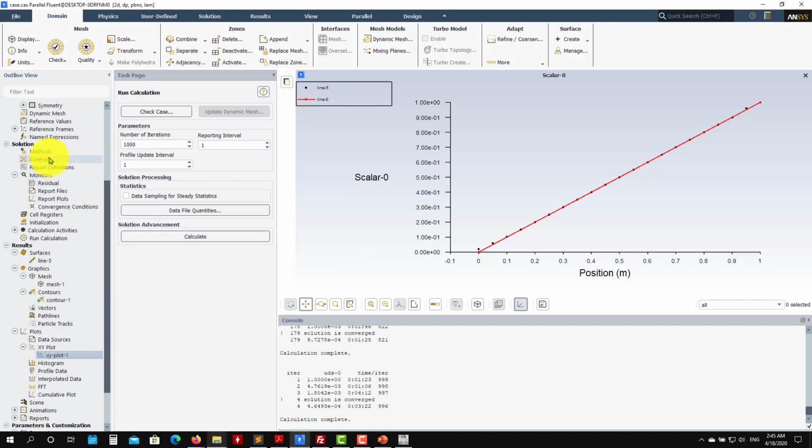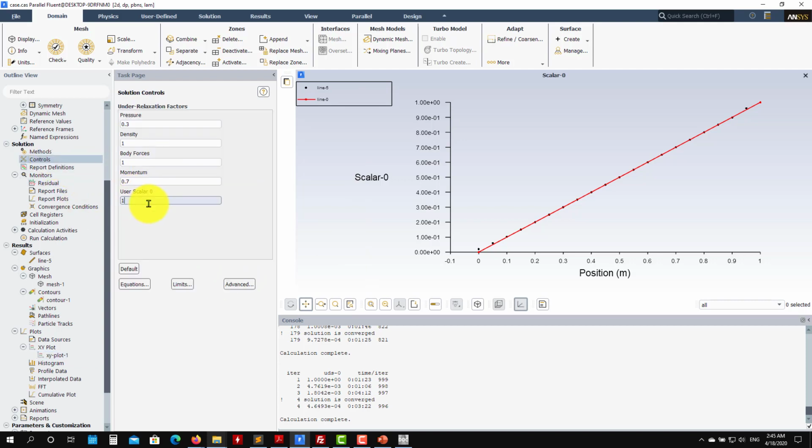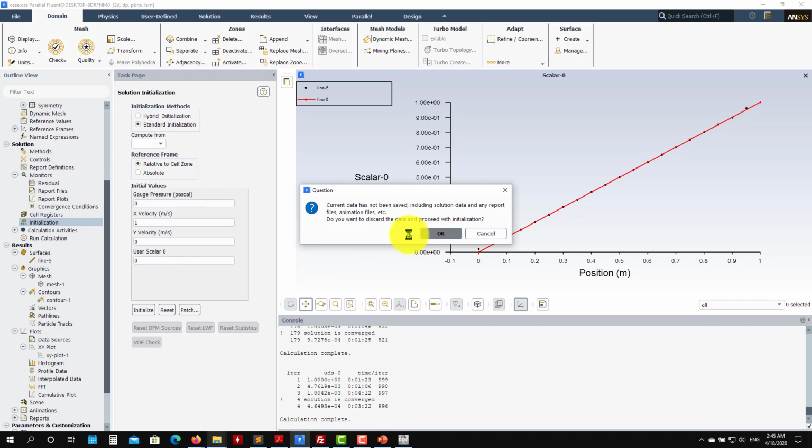Big warning, huge warning. In this case, it ran with a 1. But as you go to industrial cases, you put 1 here, and you go to another problem, even a steady one, it's likely that it might not converge or it will take longer. So see here that now I will go to a value of 0.01, much lower than 0.1. Let's see what we have.